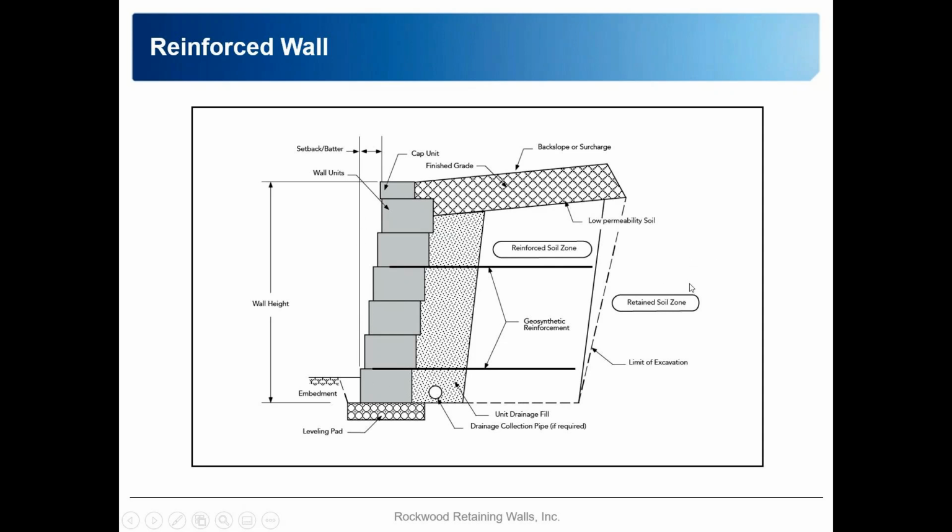You can see over here is called the retained soil zone. So it is, in essence, a gravity system, and we're using soil to help create additional weight. Reinforced soil with geogrid to create a large block that's going to retain our retained soil zone.